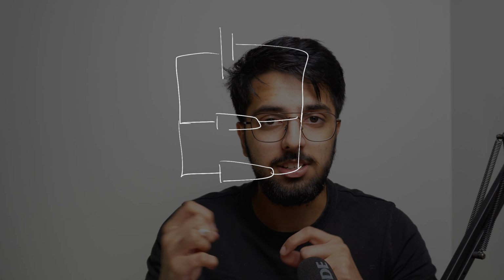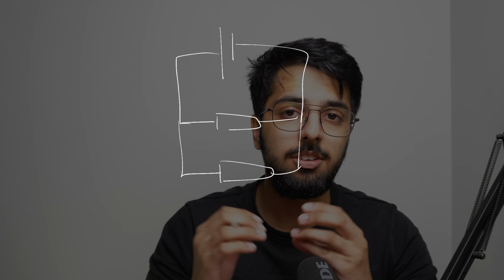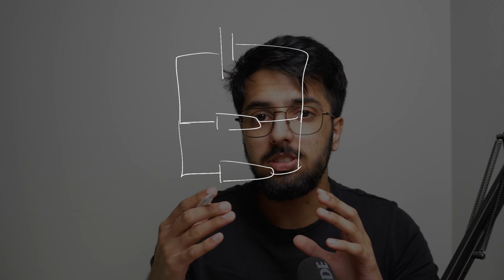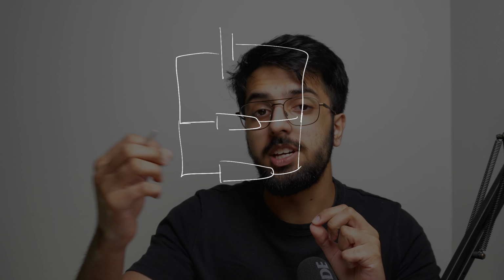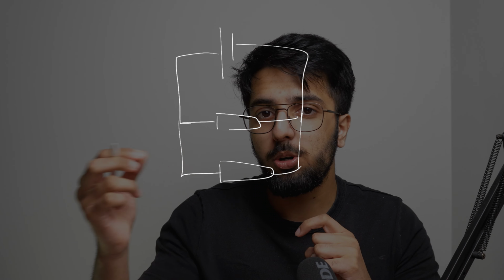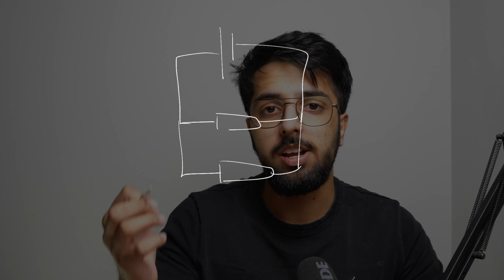Components in a circuit are said to be in parallel if and only if they're connected together by both of their ends, okay? And so what we can say is that two components are in parallel if they share both of their nodes, okay? Now, what is a node? A node within an electrical circuit is a point at which two or more components are connected together either directly or via ideal wires, okay?